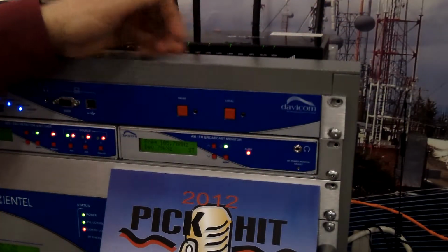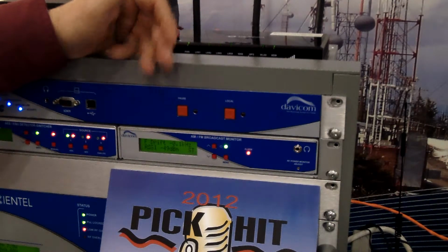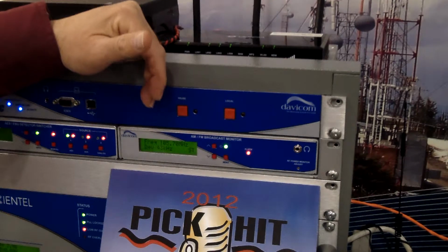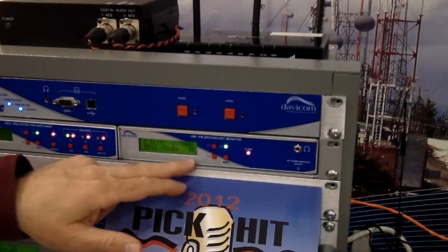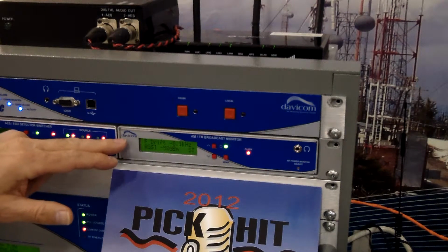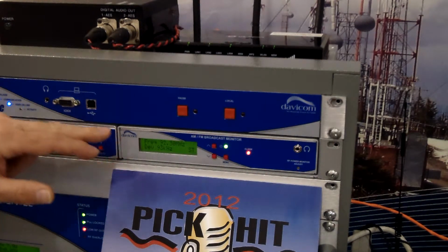the interconnection. So you see the front panel display here. In default mode it cycles between the carrier frequency, the deviation or the modulation. It indicates if stereo presence is there. It also gives you an idea of the frequency drift and the received signal strength.